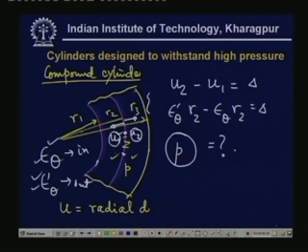So this is quite an easy exercise if you follow these steps. What we have learned is that here we can take a large pressure. Remember, because of the compressive stress developed in the inner cylinder, a large pressure could be withstood by the inner cylinder, because there was initial compression.